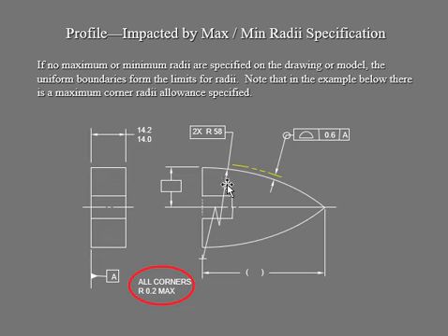This is just showing you, because of the limited space, that we use a zigzag leader line right there showing you this is going to be, your arc is going to be 2. This side and that side, it's a 58 radius for that, because look at how the arc is shaped. It looks a little pointed instead of a circle. So your center of the arc has to be really far away, because the shape of that arc is not circular. It's kind of like a little chunk of your arc. So we know that the center must be so far away.